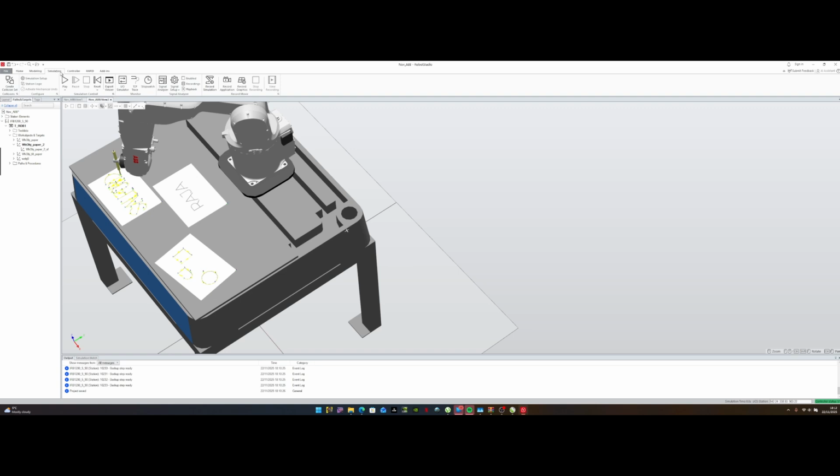I can even extend it to simulation. But once we get over to Rapid, we're now configuring or writing the actual code into the Rapid processor directly. So every time you do something in the station that you want to be reflected throughout the robot, you need to synchronize from the station to Rapid.